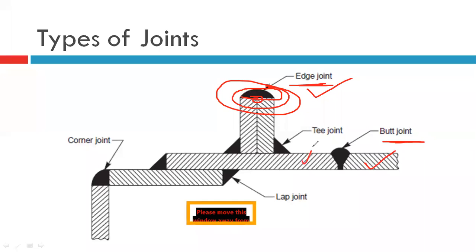Butt means the two plates face each other, front to front, so they are joining here in some portion. See, if we show it like this, the two plates, why does the slope take place? Suppose we do not make the slope, in that case the material will not get filled inside; the joint would be only here itself or up to the half portion.